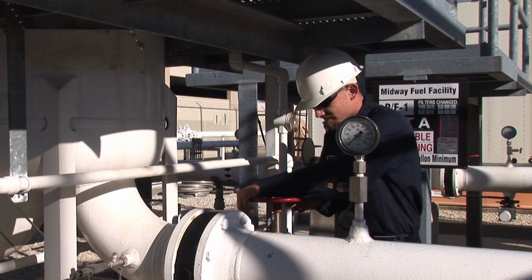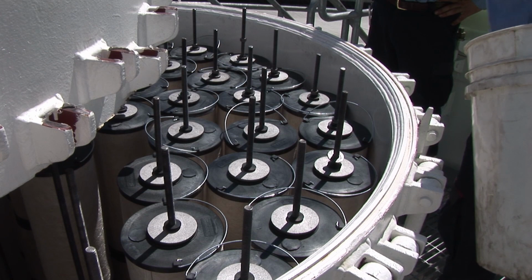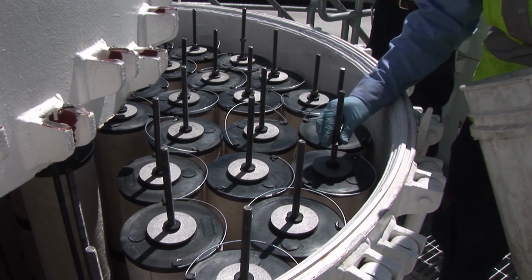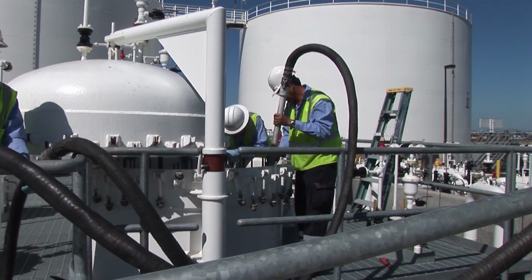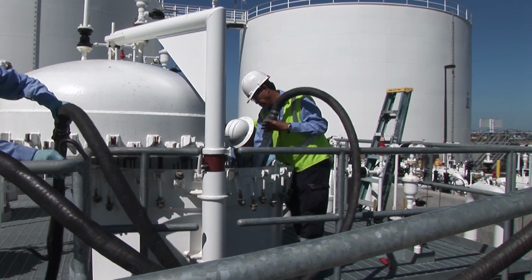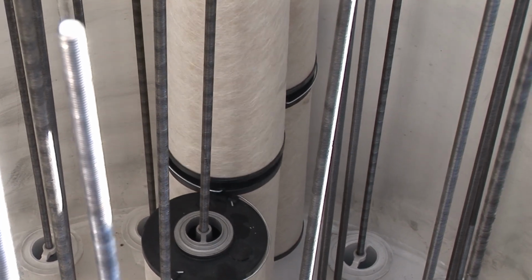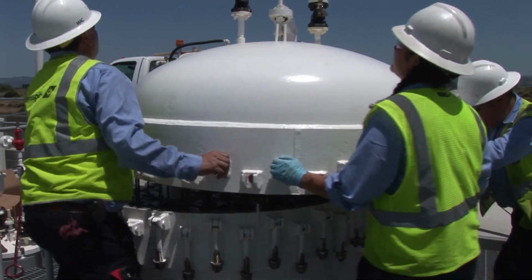Drain the vessel and relieve the system. Open the cover and remove the hardware that holds the cartridges. Remove the used cartridges. Clean the housing and mounting hardware thoroughly. Load the new clay cartridges, seal it up, and the job's done.